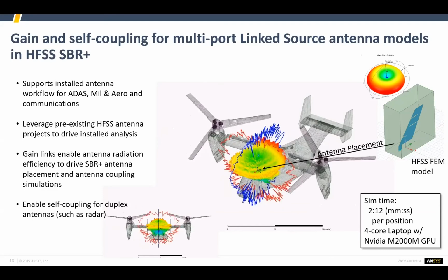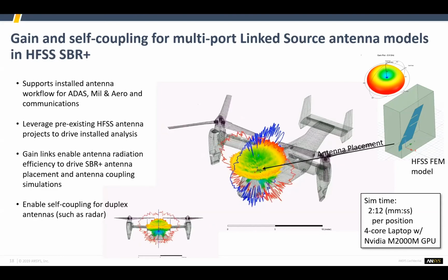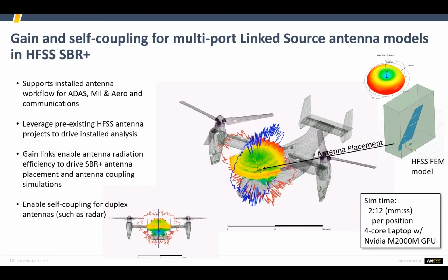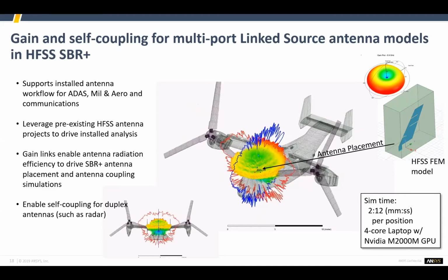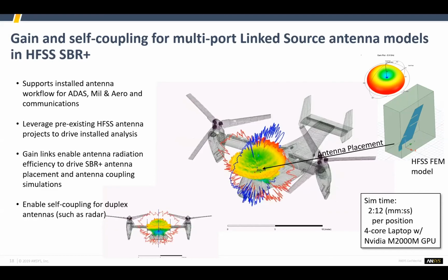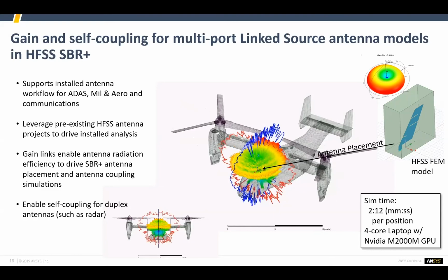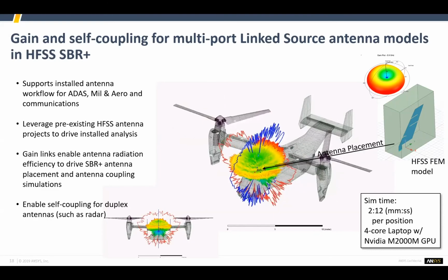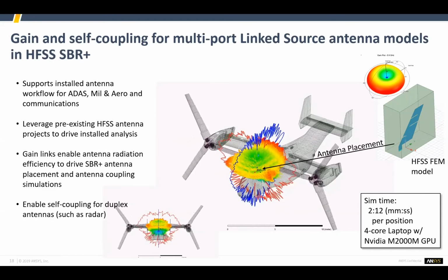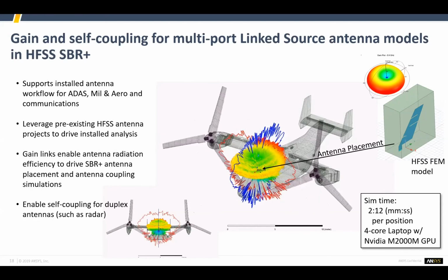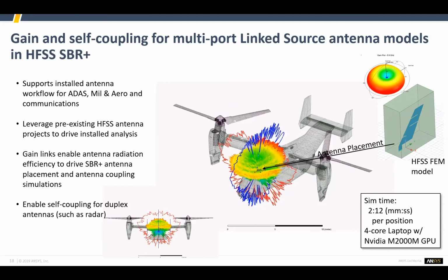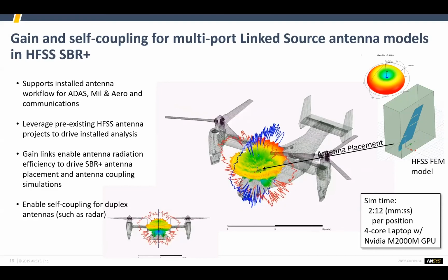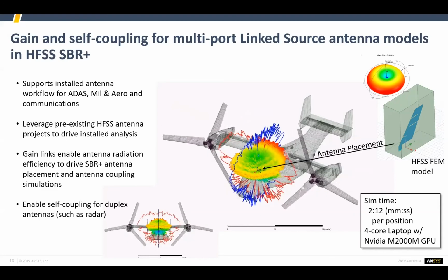We can also look at data transfer, how much data is leaking into our receiver that shouldn't be. Pretty much anything that you could test for. Once we have a simulation that uses SBR and HFSS together, pretty much anything that you can test, we can simulate. So before you put your prototype antenna on a very expensive platform, you could develop a virtual prototype that has all the functionality of the actual device from an electromagnetic perspective, and we can see how that device is going to work.